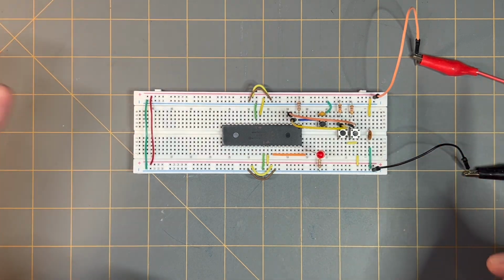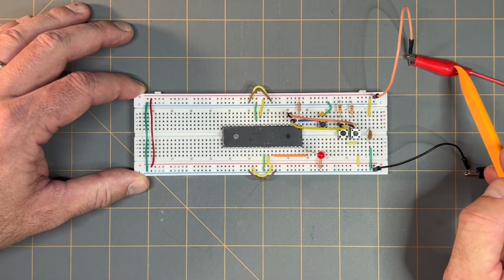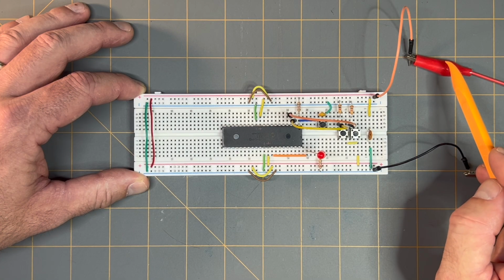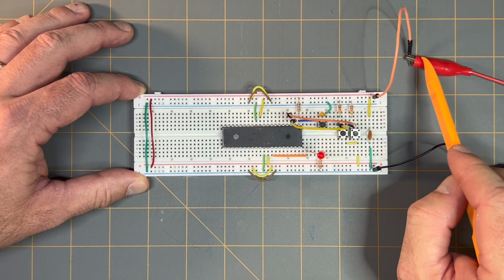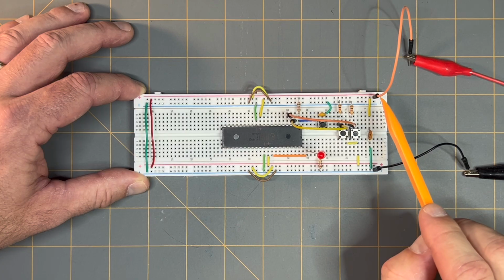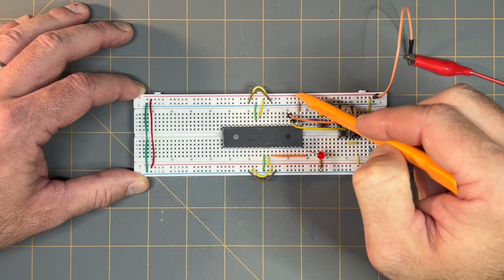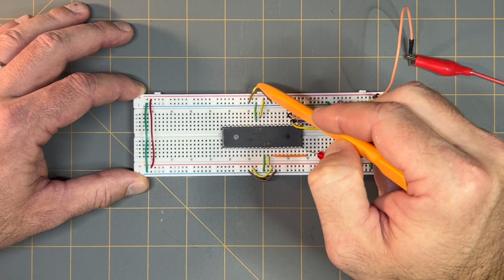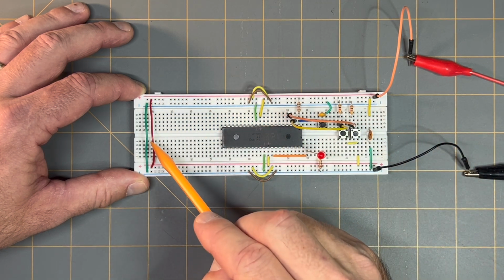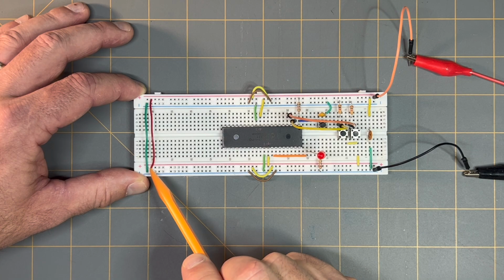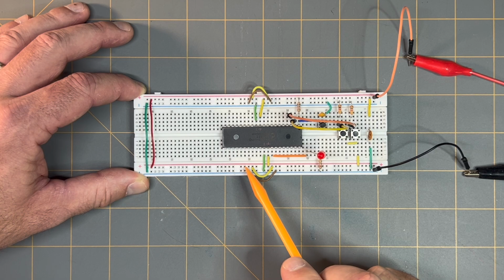So to recap what's going on there: once the power supply is turned on later to turn the circuitry on, you have your positive side connection going through this orange jumper wire, continuing down this side of the positive power rail through this yellow jumper wire to the other side of the positive power rail, across this red jumper wire to this end of the positive power rail on the opposite side of the breadboard.